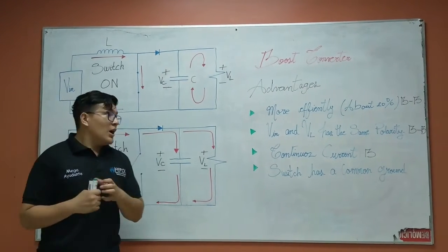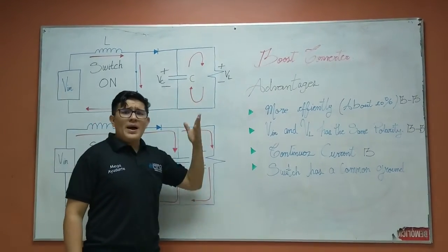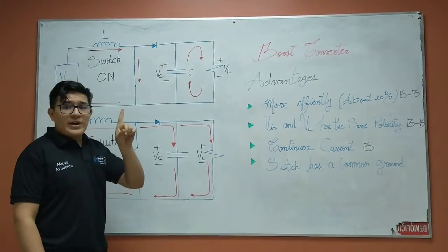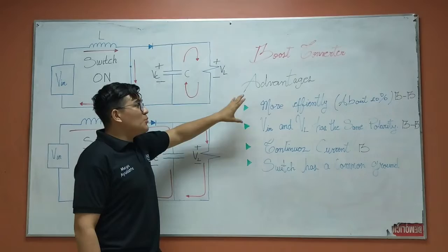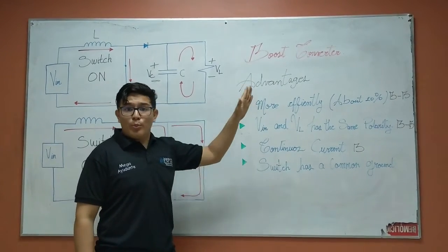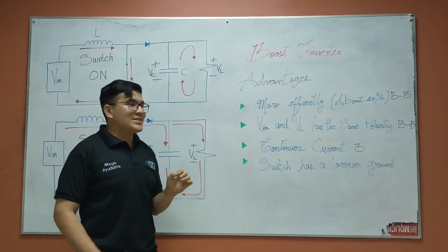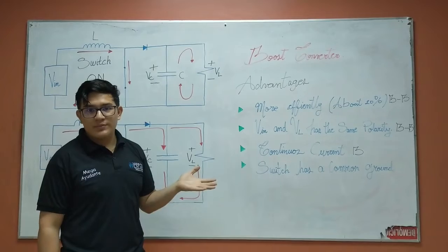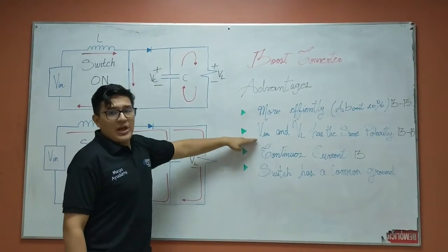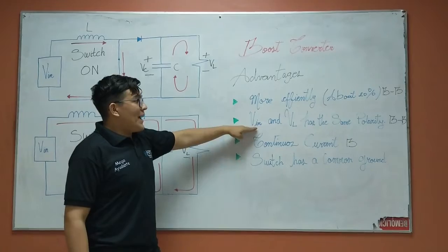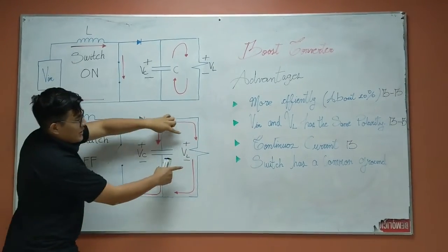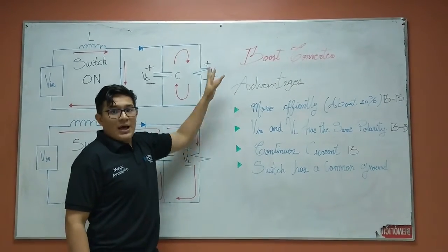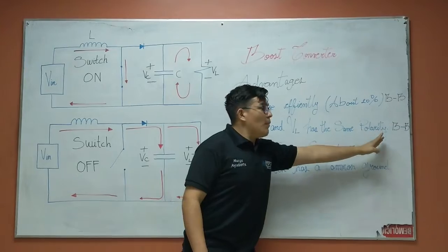Okay, finally, I'm going to explain the advantages of the boost converter over the other converter. First, the boost converter is more efficient than the other converter, which is 10% less efficient. Second, the input voltage has the same polarity as the voltage on the load. And this is a property of the boost converter. And this doesn't happen with the other converter.